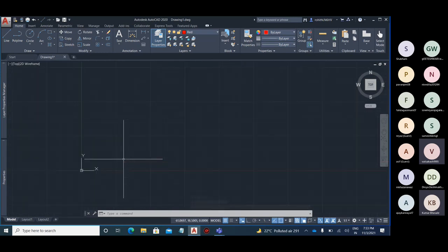As you said, we can shift the UCS to that particular point. So that will be the difference of the UCS one. What if we don't change? We started AutoCAD with that as our UCS x-axis and y-axis, and from a random point we just zoom out and start drafting. What will be the difference? There is no difference, but it affects the coordinates it will be taking.